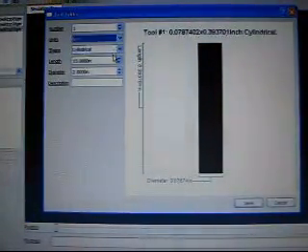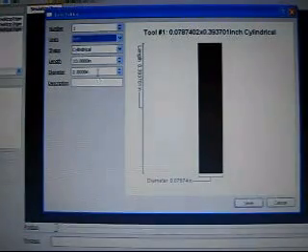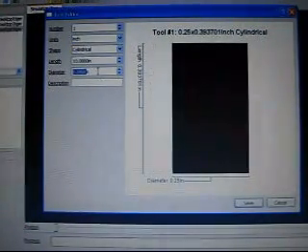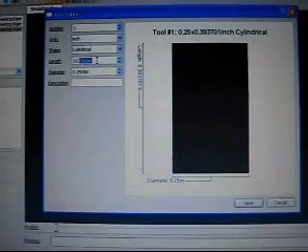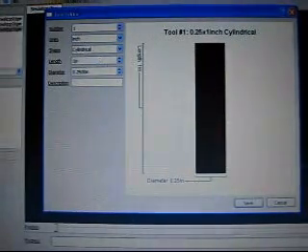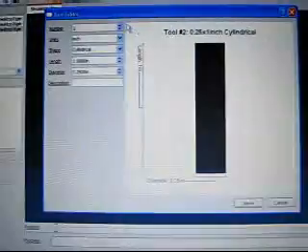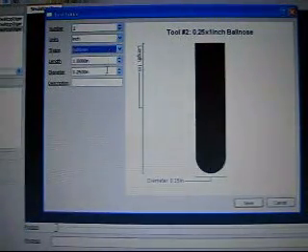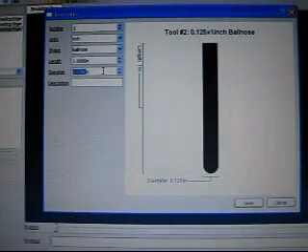It's in inches. It's a flat tool, and it's going to be 1/4 of an inch. Okay, 10 inches is a little big for that. I'll make it 1 inch. Alright, save it. Tool number 2, new tool. Tool number 2 is going to be our ball nose tool, and remember that's 1/8 of an inch.